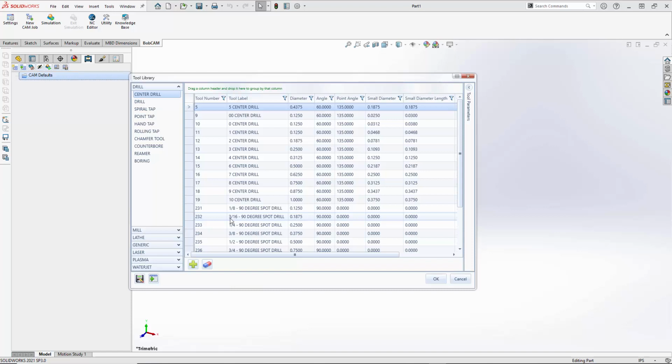Later on, when we get into the tutorials for these, we're going to create tool cribs. Now, tool cribs are the tools that you've taken off the shelf or pulled out of that drawer and actually loaded into the machine. They're the tools that we're going to be using to machine the part we're working on. So the tool crib is just to set up the entire carousel for the machine, but the tool library contains all of the tools in the system.